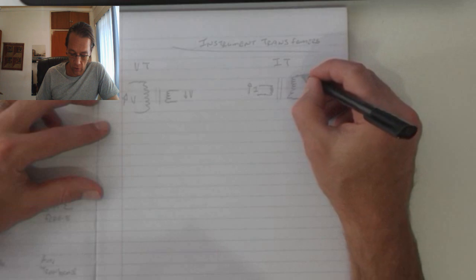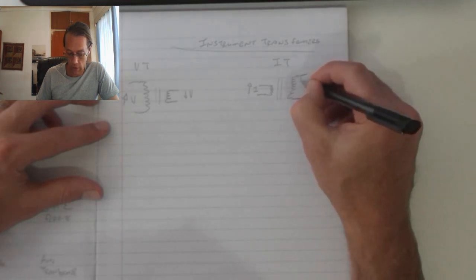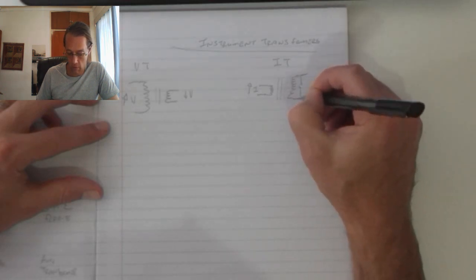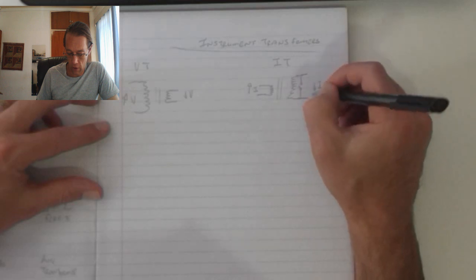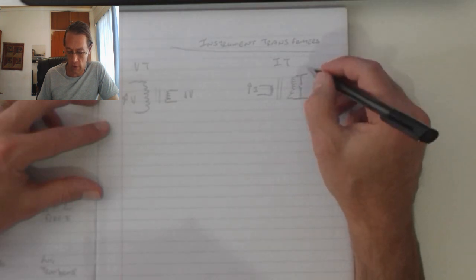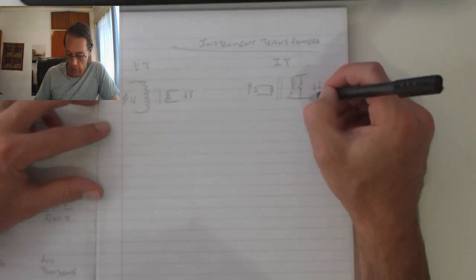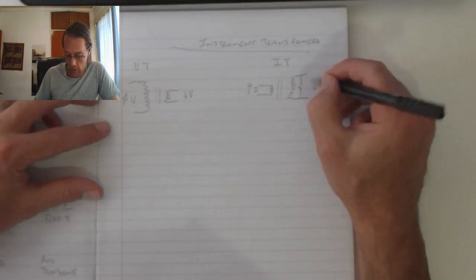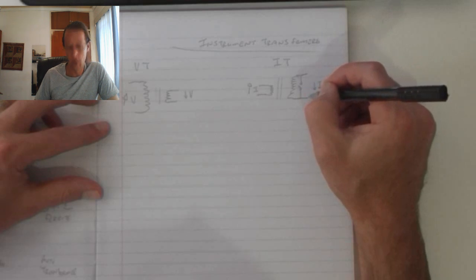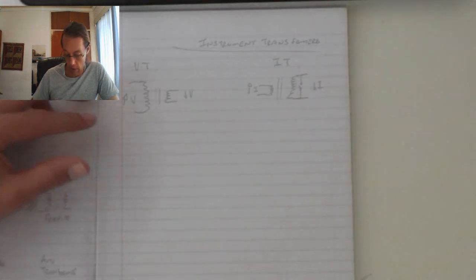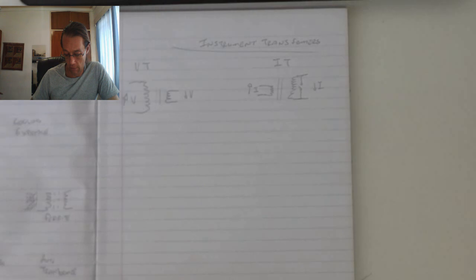It is important that on this side you connect a bypass switch that needs to be closed before you can connect your meter, in order to serve as a protection device.